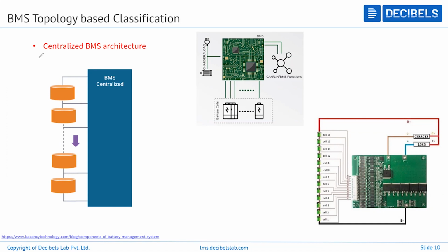So why has this topology been derived? Let me explain that. When I talk about BMS, for example a 48-volt architecture vehicle, as I said, you need at least 13 to 14 cells in series to achieve this value, 13 to 14 cells of nominal voltage.